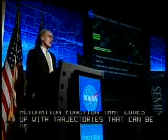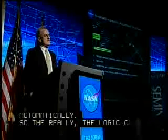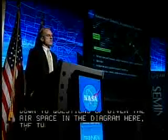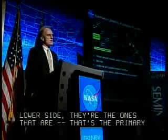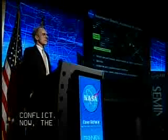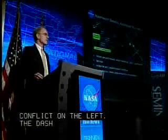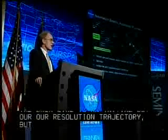So really the logic comes down to questions of, given the airspace in the diagram here, the 2 blue aircraft on the lower side are the ones that have the primary conflict. Now the blue aircraft on the lower right also has a secondary conflict with the green aircraft coming in from the left. The dashed line is an initial cut at a resolution trajectory, but you can see that resolution trajectory creates another conflict with the orange aircraft coming up from the top.